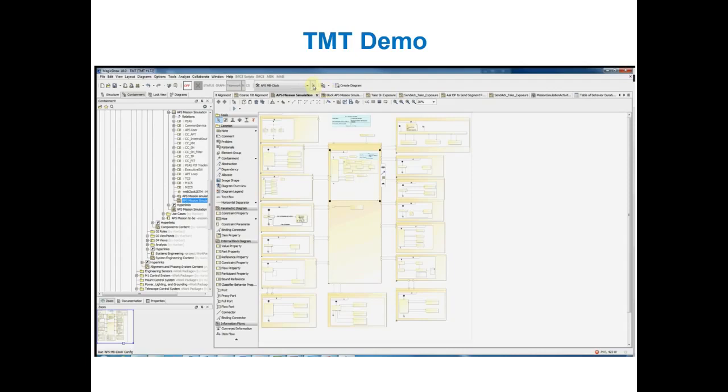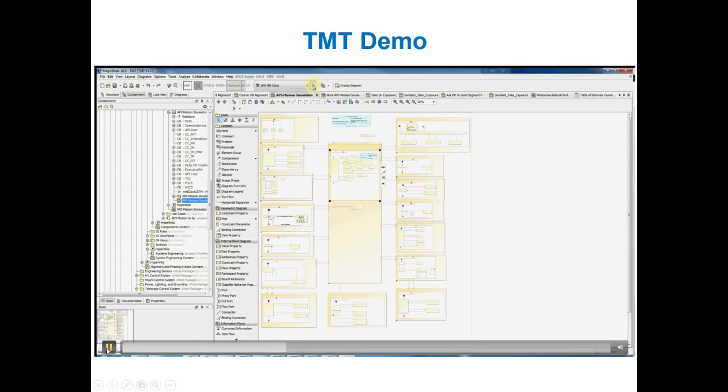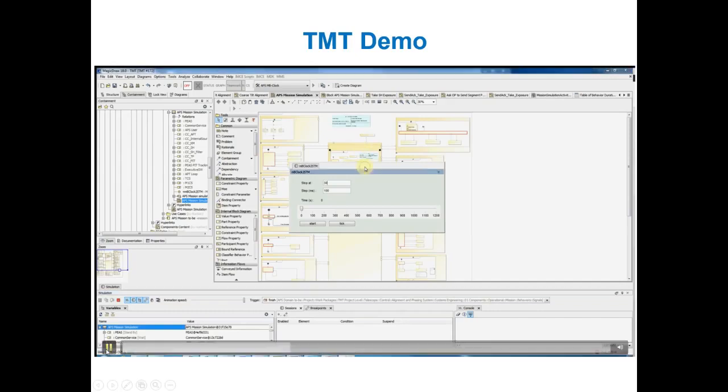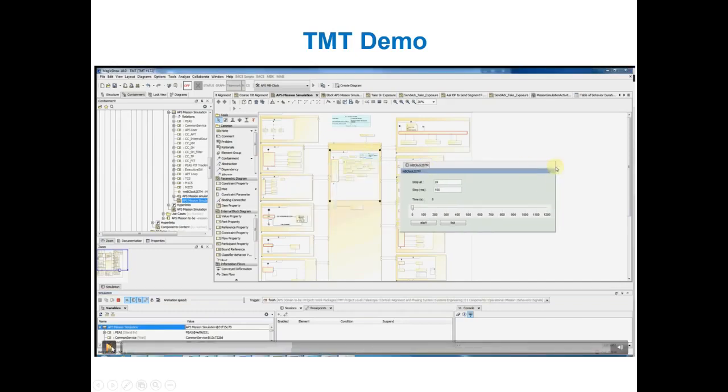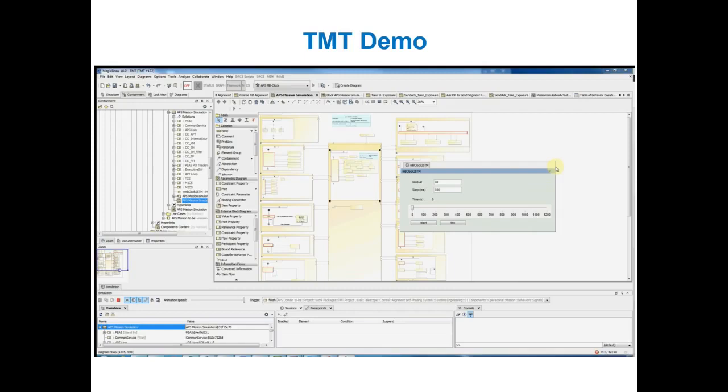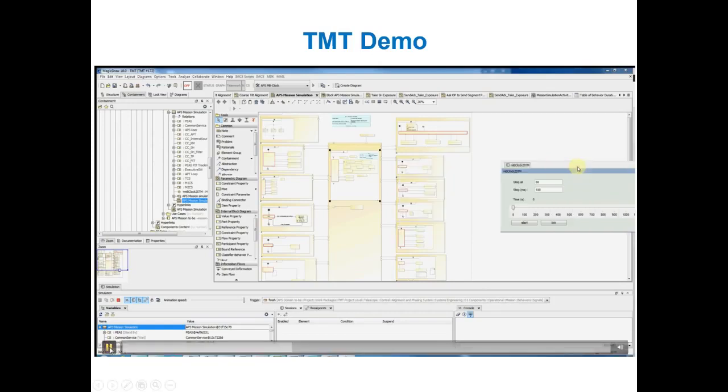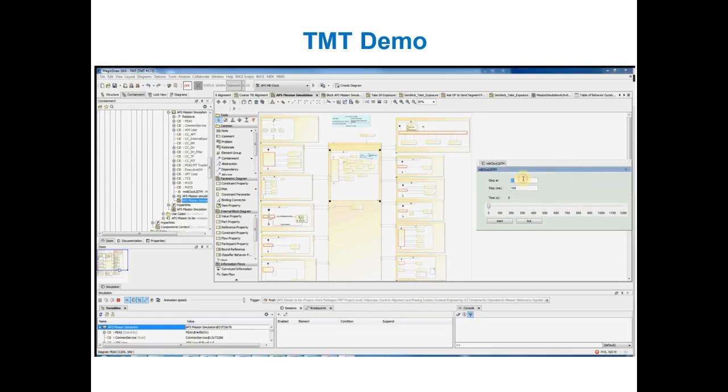So when you start the simulation, it is based using a model-based clock, as I said. So you would be able to specify here with this little GUI time for how long the simulation should run. So you're able basically to control the time. And also the ratio, like you would say 1 second of simulation time corresponds to like 100 milliseconds of actual run time on my computer. So it's like a kind of a time machine. Say, okay, how does the system look at a specified time? So here I enter 400 seconds, it would stop the simulation at 400 seconds, and the ratio would be 50 milliseconds per second.